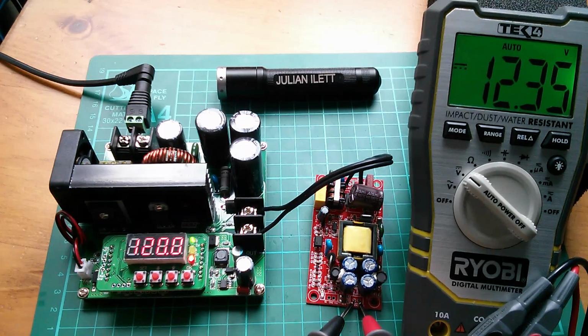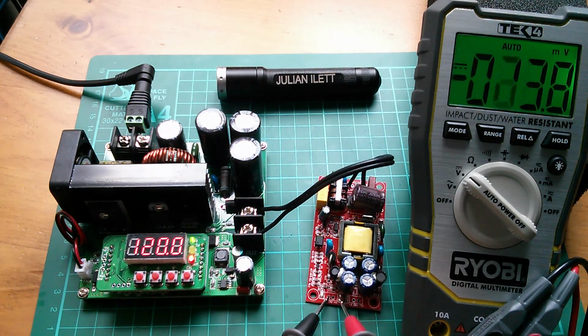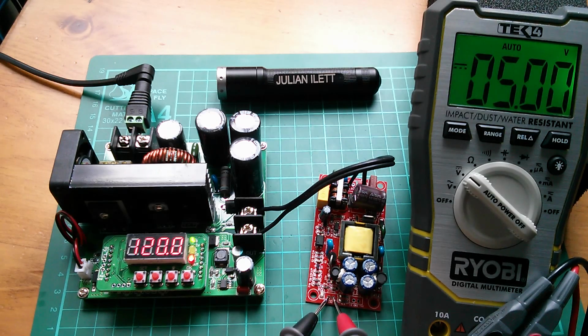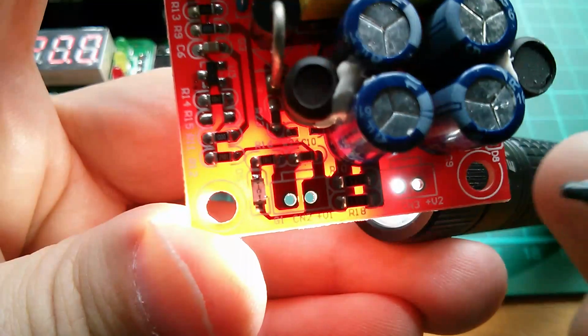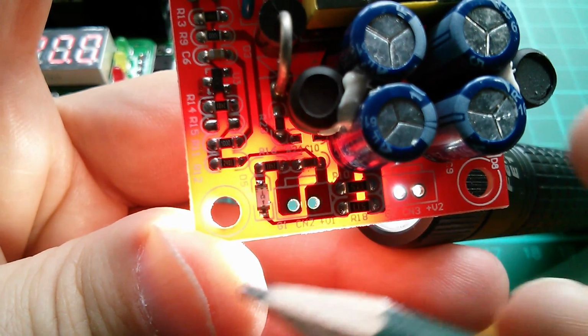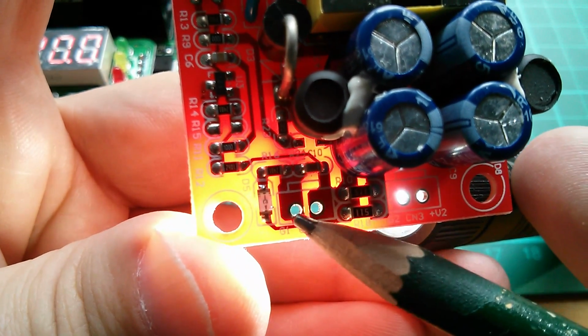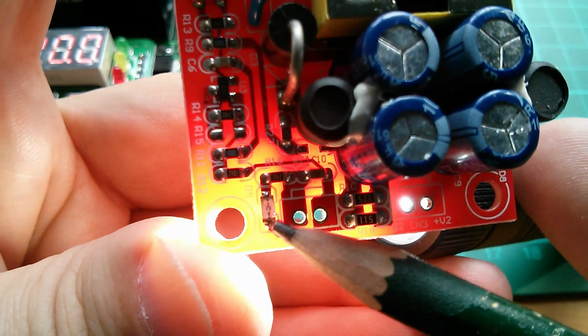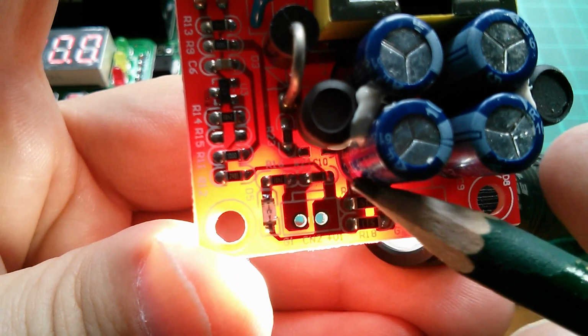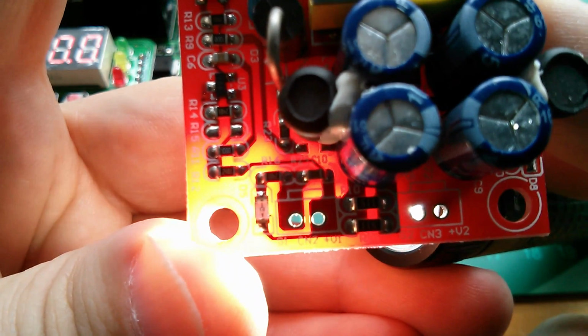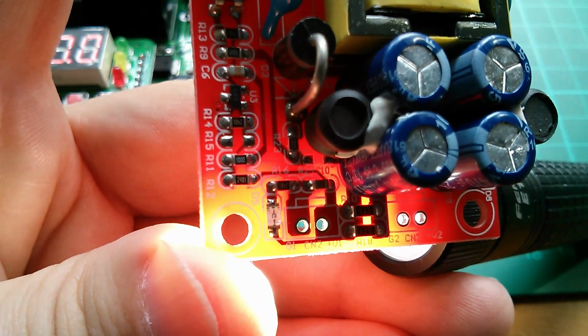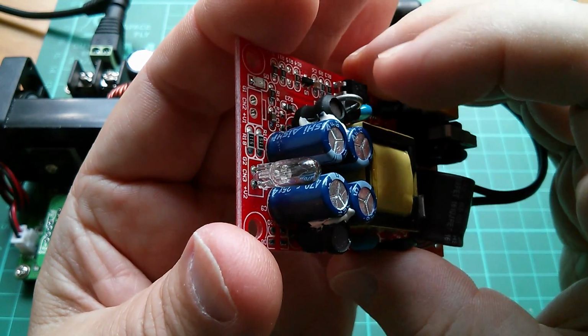That's interesting. So why doesn't that little LED come on? Well, that does seem to be working then. We've got 5 volts and 12 volts coming out of that converter. So maybe it does work. I'm not quite sure why that LED doesn't light up. You can see quite clearly that it's wired across this output. This track runs to the LED, that goes through a resistor to the other side. So has that LED been put on the wrong way round or something? That would be annoying.